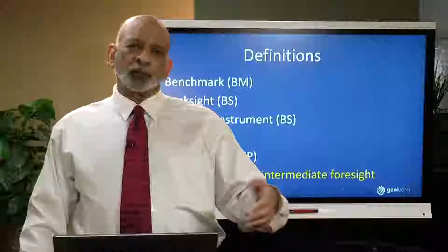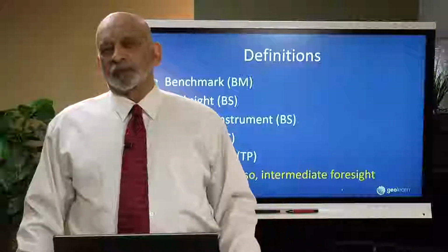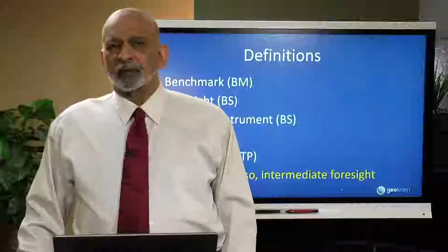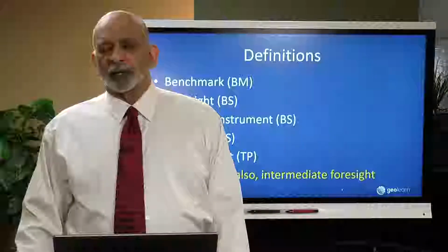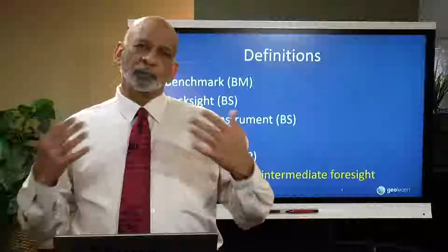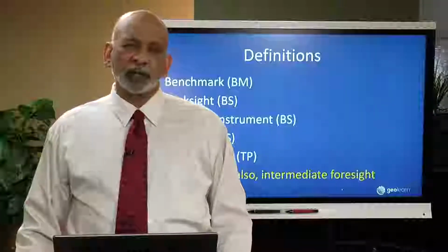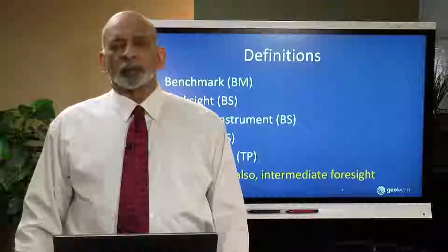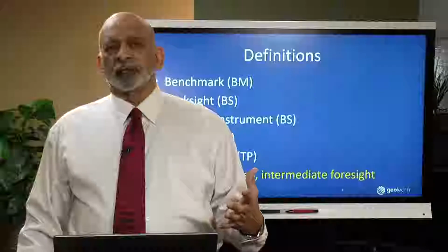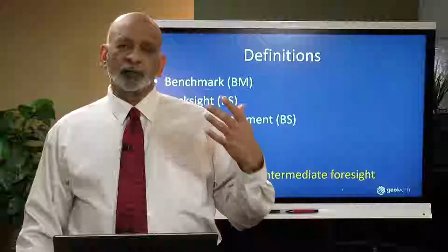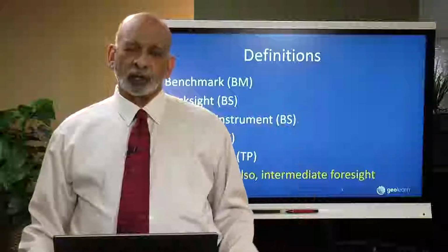But sometimes they're set by utilities, they're set by city government, they might be set by state government, and the various departments actually within the federal government also set benchmarks across the country. You always need to check very carefully to make sure you're using the right one if you need to be fitting into the datum system that somebody else created. But what's very common in engineering projects is that the first surveyor there may have already set up a benchmark. You need to find that benchmark, observe it, so that your leveling is done along the same datum that somebody else has done.